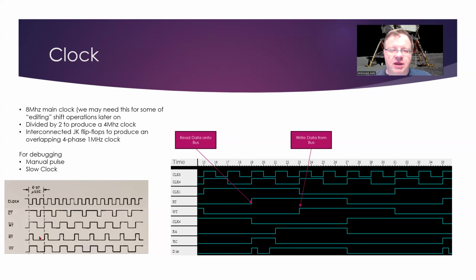There are a bunch of other timing pulses and signals that the original AGC developed. One thing we'll get into later is some of the timers, or what they call the divider. There are a bunch of almost clock signals that are used for measuring the amount of time that has passed, and there are certain interrupts that are generated after a certain amount of time. Some of that is for real-time clocks, so you can actually have real hours, days, and mission elapsed time in the computer.